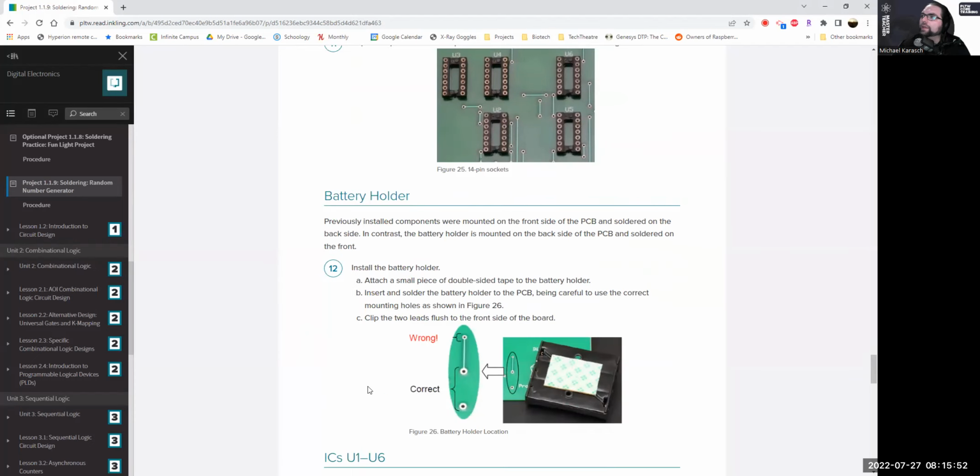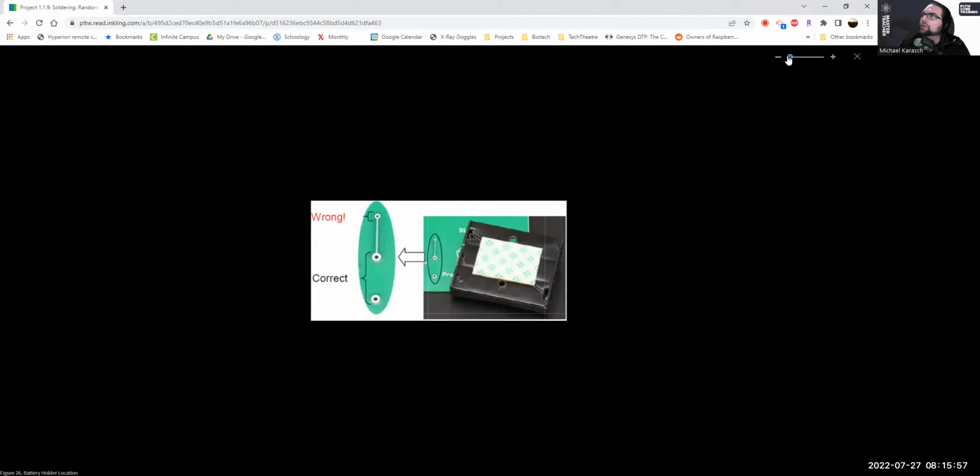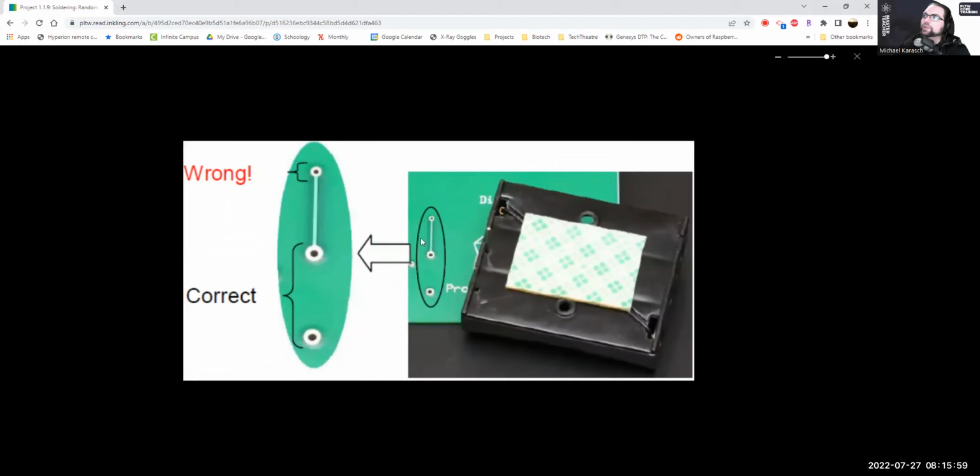The other one, and again, there's a big point on it here, but of course, reading is hard. There are these 3 holes right next to each other. The battery snap goes in these bottom 2 holes. That's the one it goes into. You'll notice this little line here. See this little line? That's a copper trace, a metal trace. It's like a wire, right? And if you put your battery snap in these 2 holes, which you can do with a little effort, it perfectly fits in here.